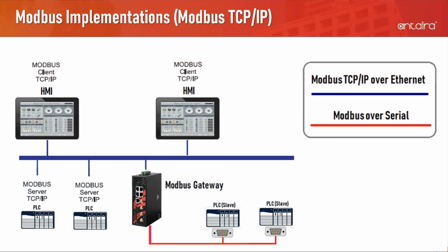Next, we'll look at Modbus TCP/IP implementation. The implementation of Modbus TCP/IP is simply that the Modbus data are encapsulated in an Ethernet TCP/IP wrapper. You might be wondering why Modbus TCP/IP combines with Ethernet. It's because of the following similarity and benefits.